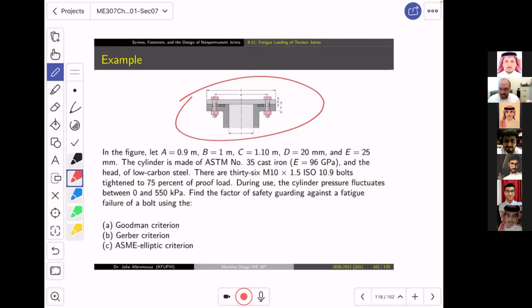And with static loading, you can turn on the power, and when the pressure goes up and static failure is a problem, you will see leaking the minute you turn it on. But fatigue, no. Fatigue deceives you.